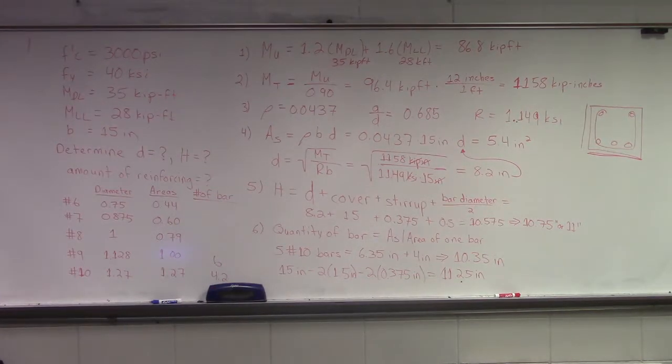Keep in mind, all we've been looking at in this instance is bending, okay? If we were really designing this beam, we'd also have to look at what's going on with its shear, what's going on with any torsion, and what other loading conditions we need to keep in mind. So it very well could be that that's what we end up working with.